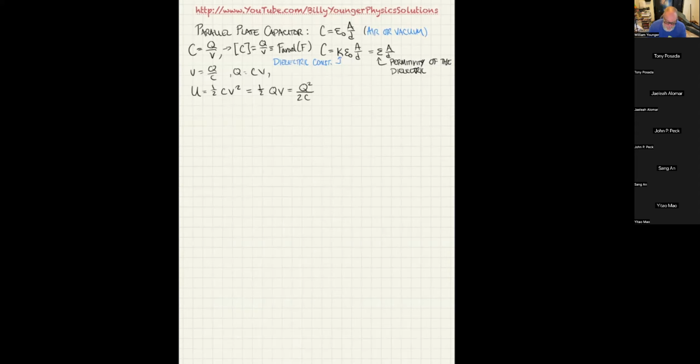Now, your book does a derivation here, or you can look up any of the videos where I talk about capacitance or introduction to capacitance on my YouTube channel. You'll see me do the derivation of the formulas for series and parallel capacitors. But basically, you don't have to memorize a new formula. It's literally the exact same formulas as you use for resistance, but in the opposite order. So for instance, 1 over C equivalent for a series circuit is 1 over C1 plus 1 over C2 plus and so on.